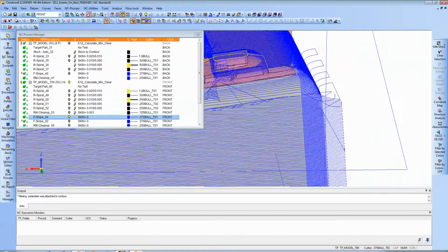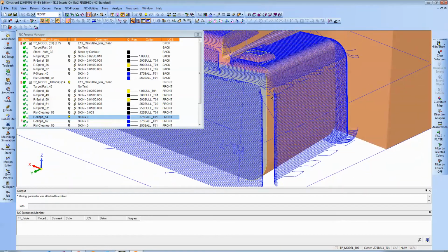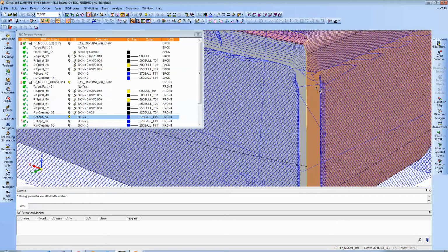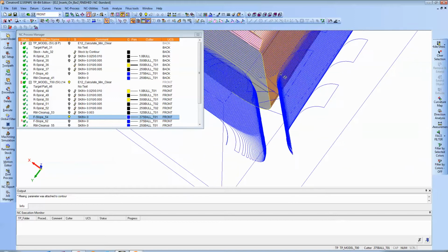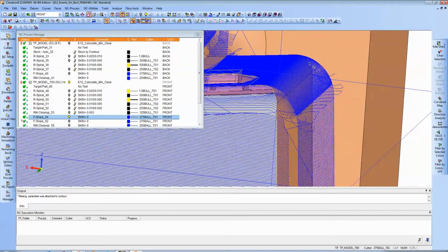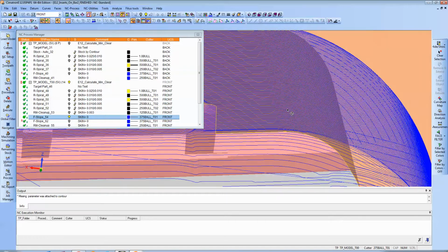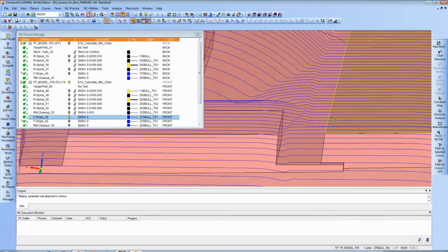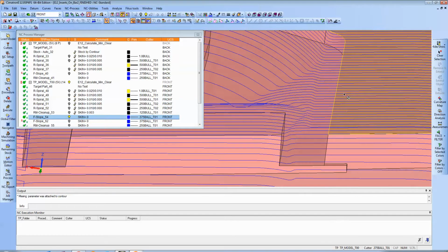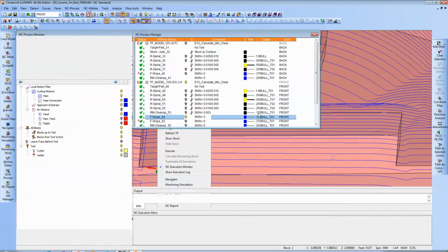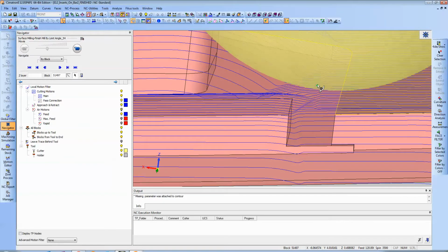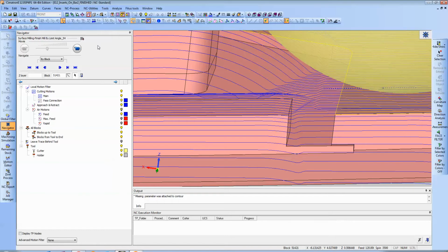And it behaves a little bit differently. Here, where the motions are Z layer, it's arcing on and off and not rolling around that edge. But in the horizontal motions, where we're doing a parallel cut, it's going to lift up ever so slightly to avoid, right here we can see it, we go to the navigator. You can see it lift up right here. To protect that edge.